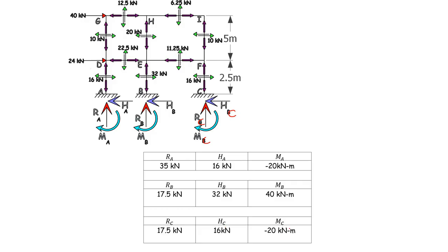So this is how we solve the portal frame using the principles of the point of contra-flexure, as well as calculations of the joints using the equilibrium equations, and using the basic concept that the interior column shares twice the shear as that of the exterior columns. Using that methodology we have solved, and we have also assumed the beam moments to be clockwise and column moments to be anti-clockwise. So using this sign convention I have solved. If you want to change the sign convention you can, but you will end up with the same answer with a negative sign. So this is how we solve the problem.